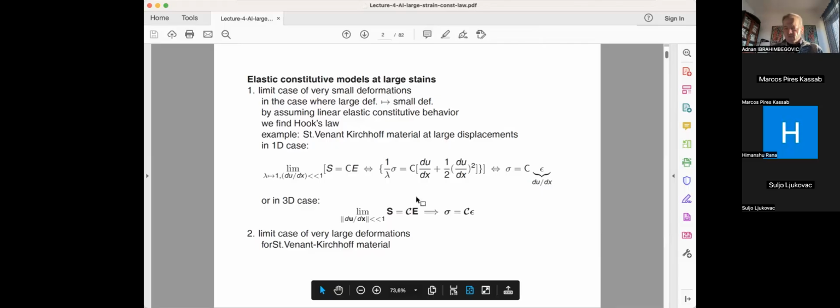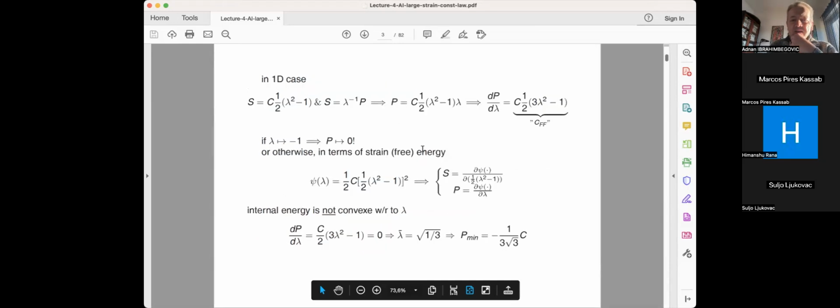And then for the 3D case, you take this elasticity tensor, you build it from the Lamé parameters lambda, mu, or whatever it is that you want to build it from. So we already mentioned that in the 1D case, this second Piola-Kirchhoff stress is connected with Young's modulus times the Green-Lagrange strain, and the fact that you want to obtain the physics of what is going on by taking into account something that looks like a true stress.